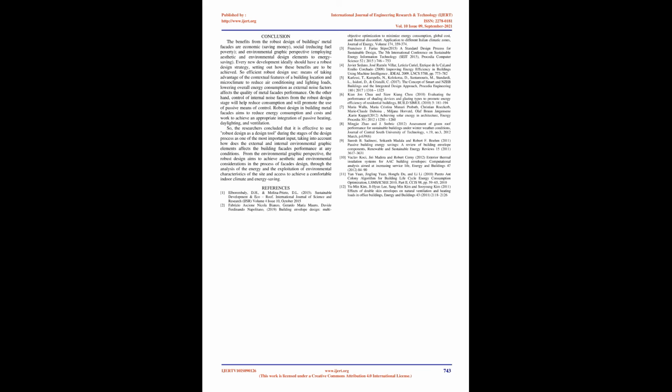Thermal insulation and energy efficient. The thermal insulation solutions present nowadays one of the key factors for the assessment of the material composition of building envelopes. One of the main design objectives is thus to reach thermal insulation properties as well as possible. This can easily be accomplished using a thermal insulation layer, whereas the most important decision is to choose a proper insulation material. The thickness of the thermal insulation layer is then calculated according to appropriate standards. Vaslav Kosi et al., 2012.